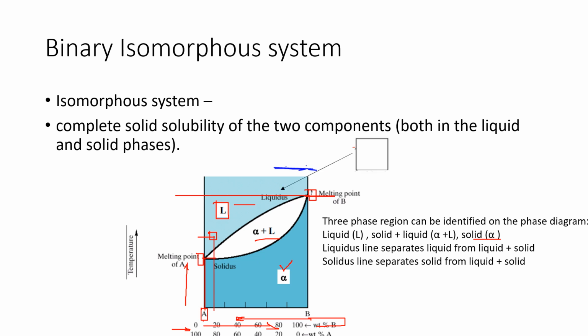Now if we talk about the microstructure at the liquidus point, this is the microstructure where the grain boundaries are completely liquid. At this position, in the mixture of liquid plus solid, this is the grain size of the solid solution, which is surrounded by the liquid solution. The small circles represent the solid grain bodies. This is the microstructure at this point.